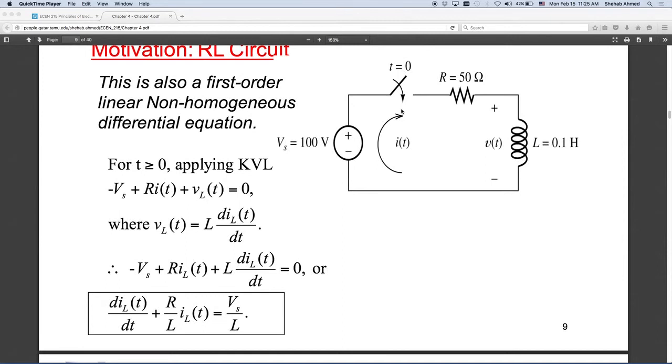How about for an inductor? Let's go back to the capacitor example. In this case, IC equals C dVc by dt. There's no voltage change with respect to time anymore, so dVc by dt is 0 and the current is equal to 0. Current is equal to 0, then it's an open circuit.